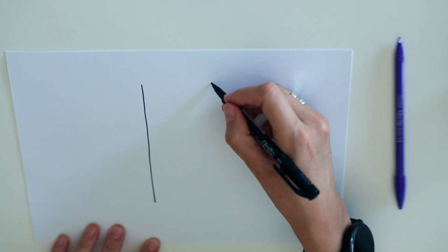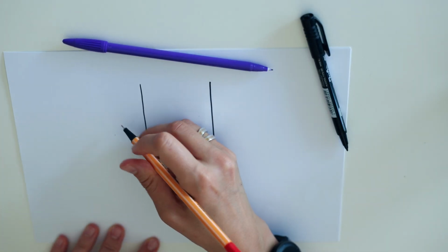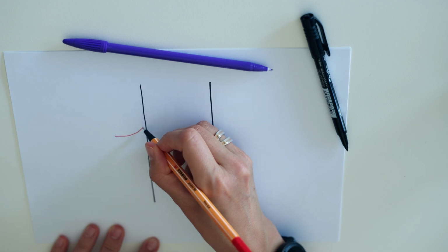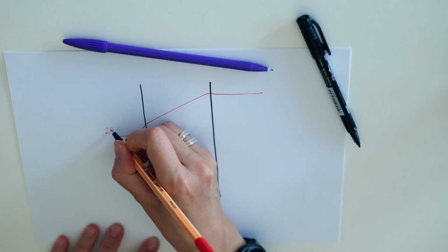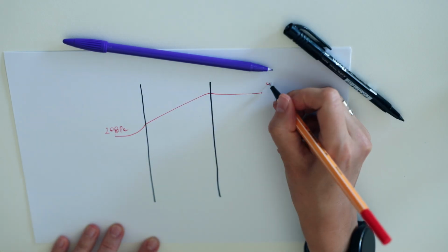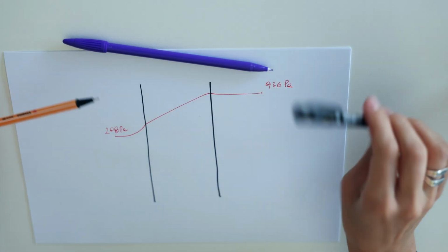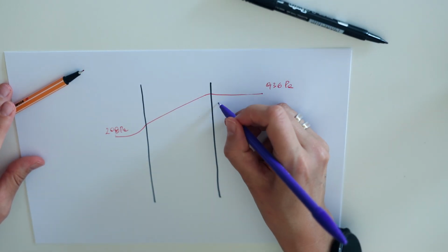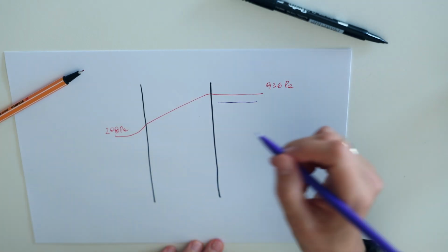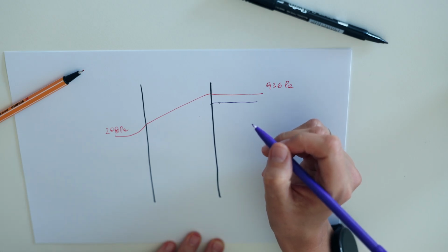So what happens when condensation occurs? We have a wall. Let's take now a solid wall for simplicity, and we can draw again the maximum pressure of saturation. That will do something like this, no? And for instance, if we take the case before, you had 208 Pascal outside, 936 Pascal inside. So we can imagine that we start with a calculated pressure that is below the saturation pressure, because there is no condensation inside the room, and then the air starts to travel across this facade.